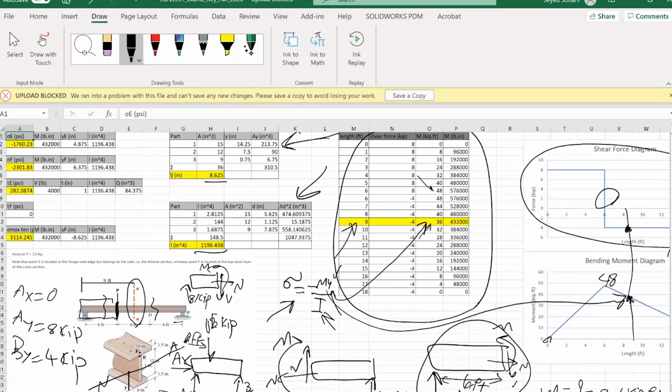Over here, this is just the pure calculation of those stresses. One thing before we talk about the numbers: on the exam, I specifically asked about the state of stress at those 2 points, compression or tension. Because these points are both above the neutral axis, they should both be under compression. As far as the calculations to obtain the values for the stresses, I would suggest that you be consistent with the units, all right?